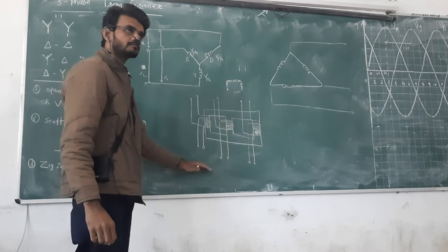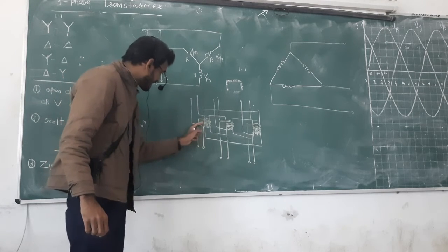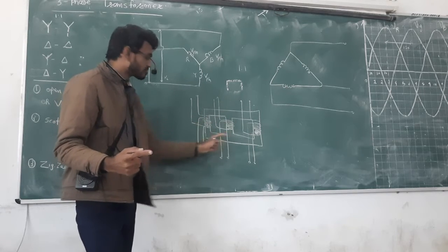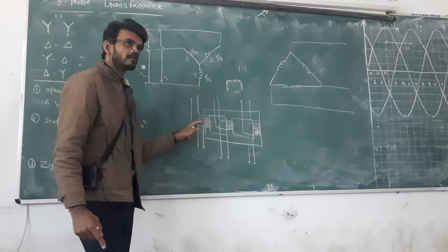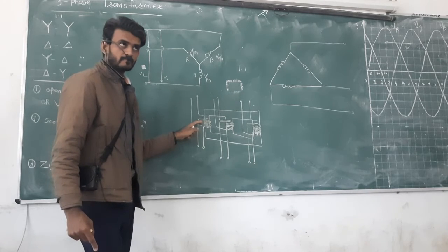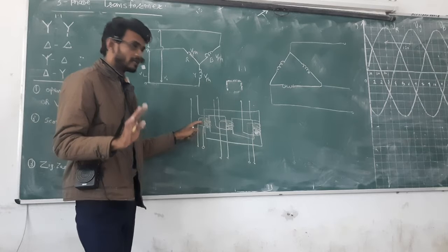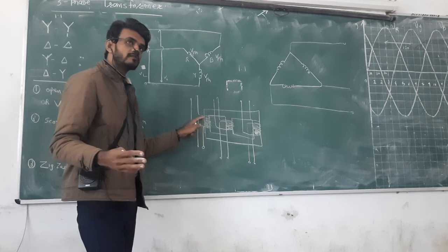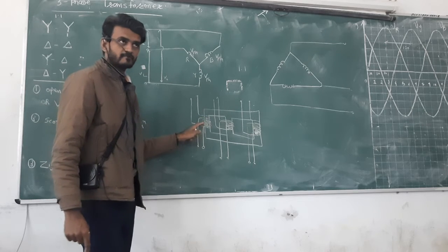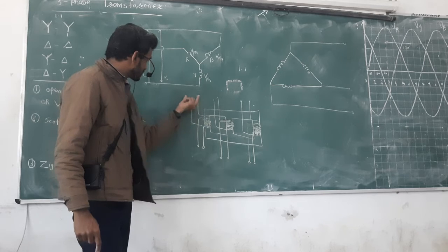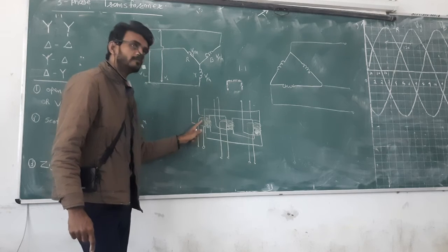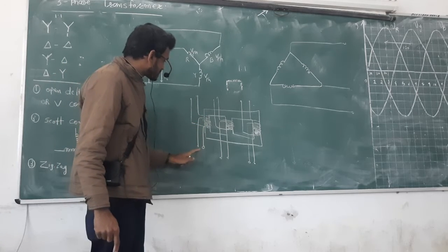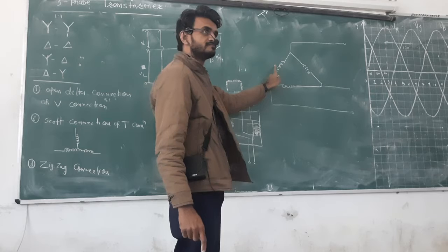Primary, secondary. Whatever the white winding induces as flux, that flux through the core links through this yellow winding. And it is a 1:1 transformer, let's say. Then whatever the voltage given to this winding, the same voltage will be induced on this yellow secondary winding. Okay, so this is the phase of the primary, this one. The yellow winding is the secondary phase, this one.